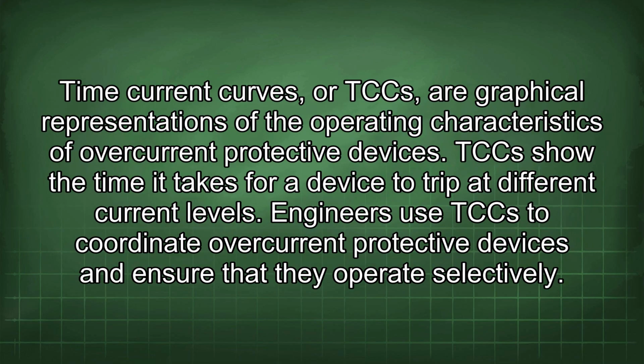Time current curves, or TCCs, are graphical representations of the operating characteristics of overcurrent protective devices. TCCs show the time it takes for a device to trip at different current levels. Engineers use TCCs to coordinate overcurrent protective devices and ensure that they operate selectively.